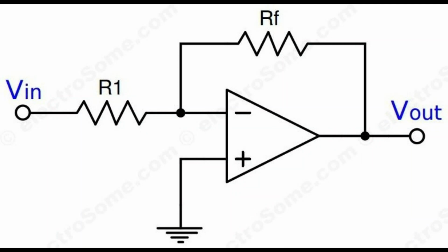Now you have completed the experiment on inverting and non-inverting amplifiers. See, now you might certainly feel that it is really very easy to design an inverting or non-inverting amplifier with the help of an op-amp. You just have to design 2 resistors only. You have to decide which are the 2 resistors that you have to connect. Given the gain of the amplifier, you have to design only the feedback resistor and the input resistor.